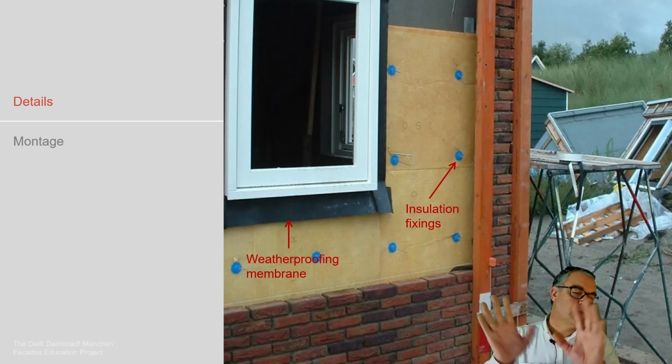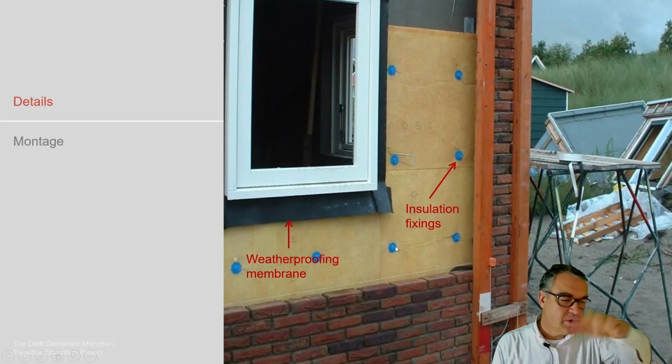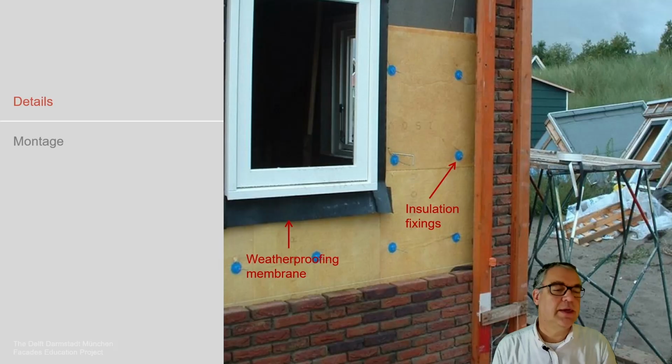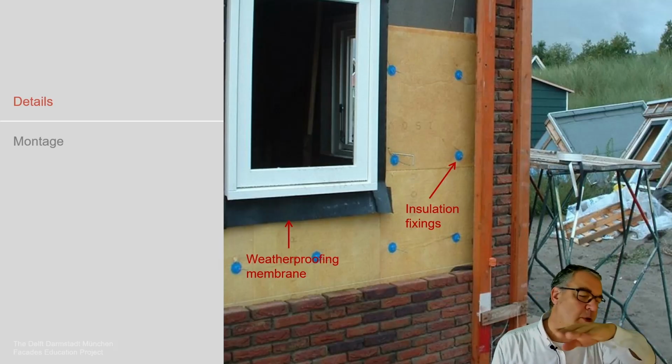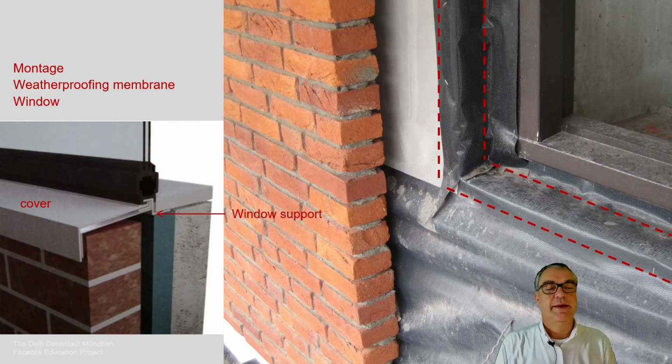This is a Dutch sample, which we can identify by seeing the window being brought in position before the masonry is brought in position, the typical Dutch way of doing it. We also see that there's a need to make sure that any leakage of the window, any water coming from the window, needs to be drained out so that no additional water gets into the cavity. It always needs to be drained with the windowsill drained to the outside of the system.